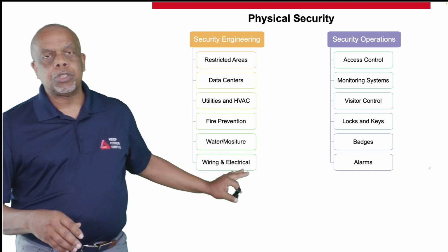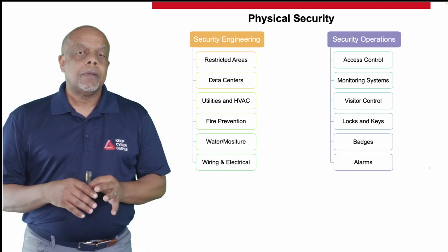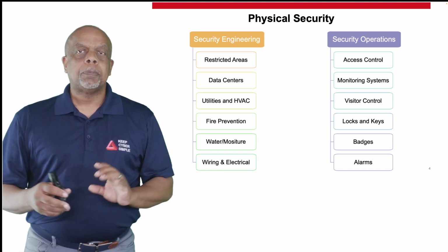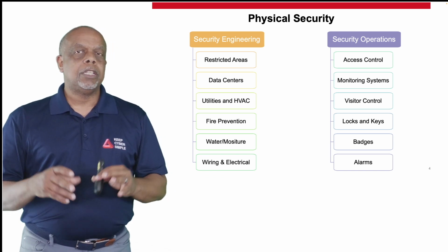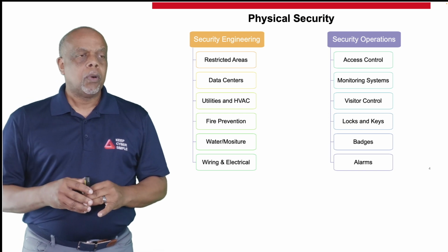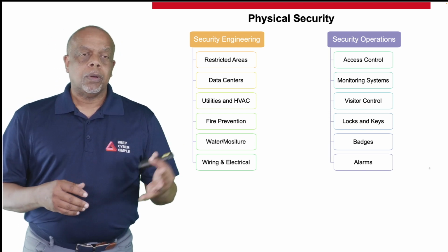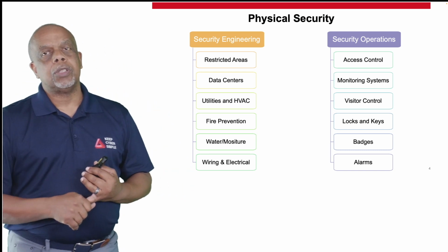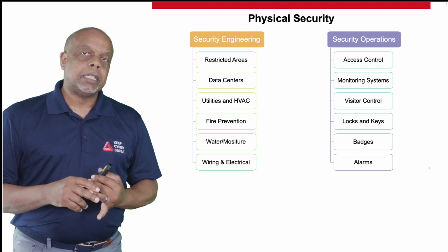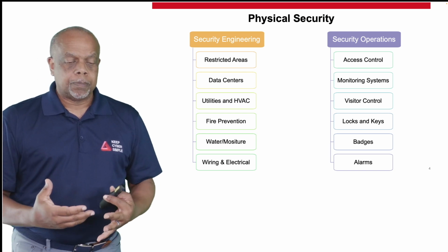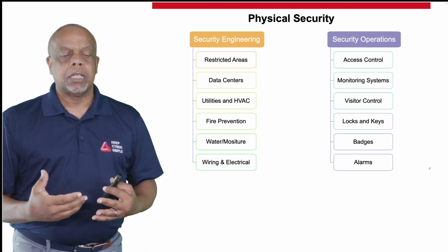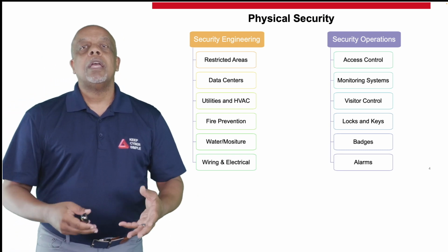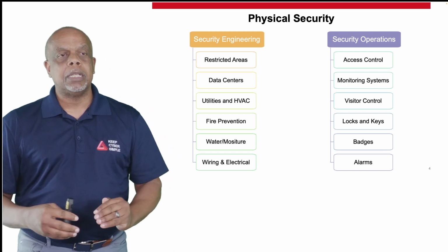Again, water and moisture, big thing. How do you keep water out of facilities? And not just water, but humidity, especially around electronics. Maintaining humidity is very important, because if the humidity becomes too high, you're susceptible to corrosion, rust, and things like that. If the humidity is too low, then you're susceptible to more static electricity, static charges as you're walking across carpets and rugs. That's what gives you that static charge many times, because the humidity is off.